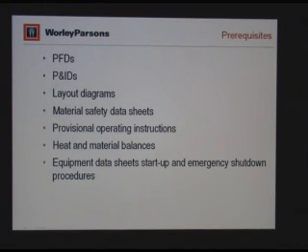And also we need to have provisional operating instructions. A lot of times that's not available, and that's why we put into recommendations during HAZOP that the operating procedures need to take care of this issue, that issue, so that helps them identify the key issues they need to address when they're writing the operating procedures.